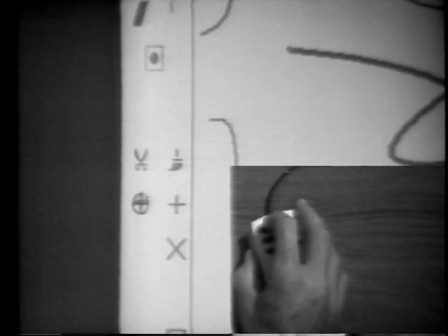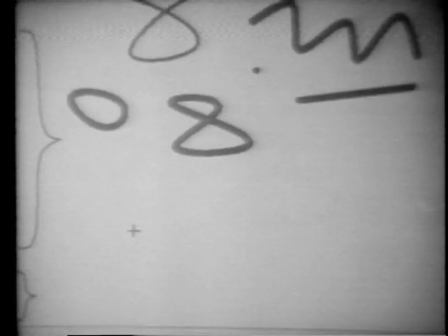This command is quite similar. However, it will generate closed curves. The 3 switches of the cursor control device, called the mouse, have different functions when defining knots. The top switch places a knot at the exact position of the cursor.